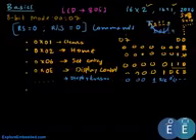Now the next command is an important one. The one shifts here. Now this bit is called D/L. This defines the interface length. If you are using the LCD in 8-bit mode, this would be 1. If you are using 4-bit mode, this would be 0. Now the next bit is called N, number of lines. If it is 0, it is a one line display. If it is 1, it is a 2-line display.